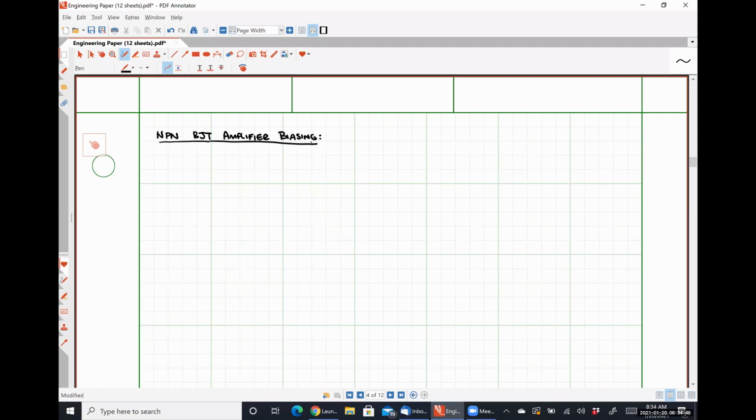In saturation, we don't get that amplification. So we're trying to figure out effectively what the rules are for these different schemes to force the circuit to be in the forward active region, or at worst case scenario, soft saturation, where it still behaves roughly like forward active.